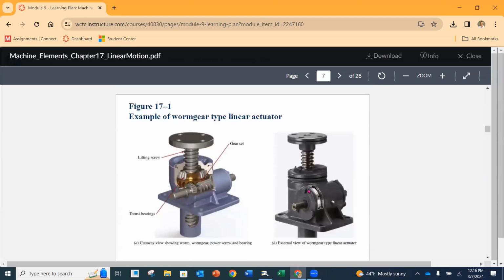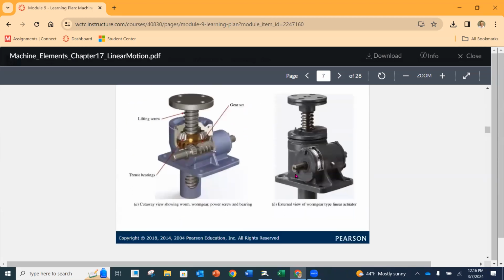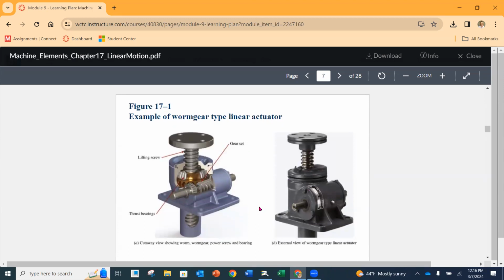Keep going. Another example of a place that we can use these linear motion type of lead screws is in the form of a jack, as we see here. In this case, we've got a worm gear that rotates this collar around here, and then you can see that the lead screw is on the inside, and that's going to control the height of the platform or the jack going up and then reversing and going back down. Okay, so another really good application as we see here.